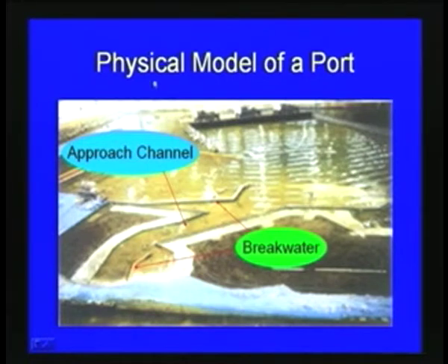The next case is the physical model of a port. You can see that the various channels and the breakwater are replicated in the model with appropriate scaling. Then we can see what happens when a ship comes or if a new construction is made, and the waves will also be simulated here, and in case tidal effects are there, those are also simulated in this kind of model.